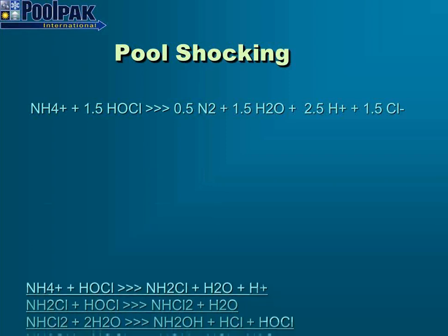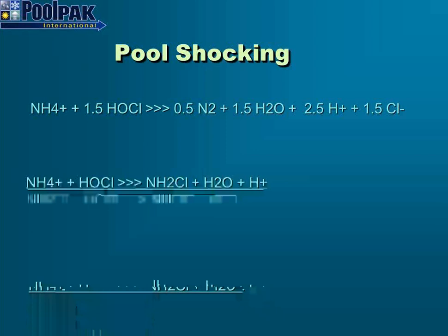Pool managers are well trained in this, and again, this is their responsibility. It's a team effort. We take care of the air in terms of heating, cooling, dehumidification, and ventilation. The pool manager and the owner are responsible for taking care of the water. And again, once we have a problem, we do have to increase that chlorine level to 10 times the combined chlorine level, and that will force some of the chloramines and other substances out into the air so they can be ventilated out of the room or purged out of the room via the PoolPak unit.